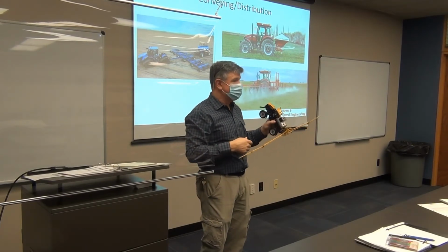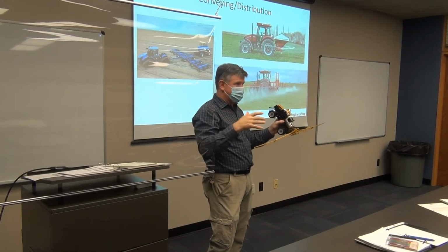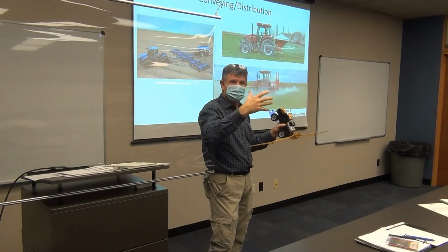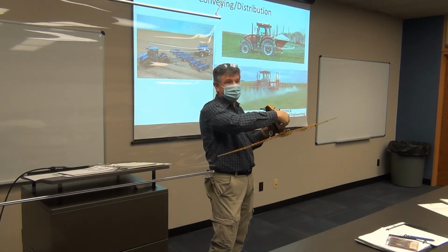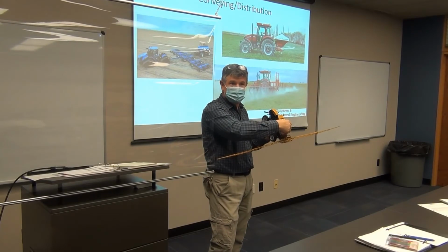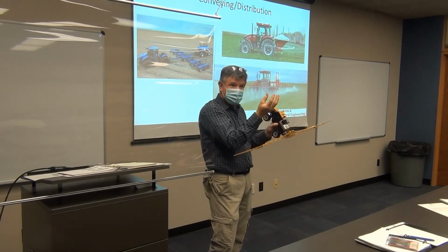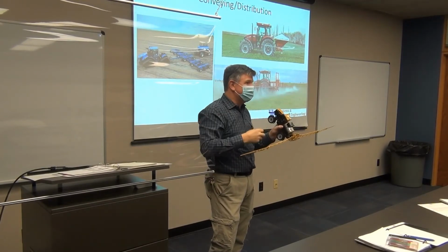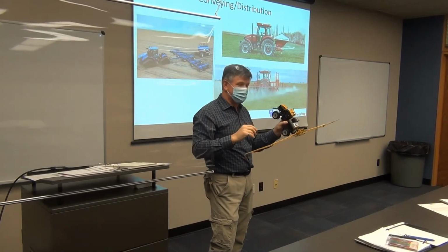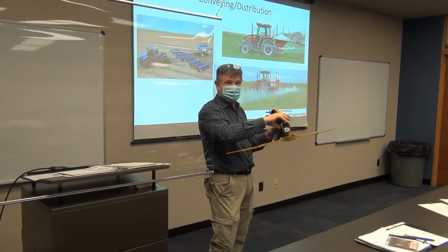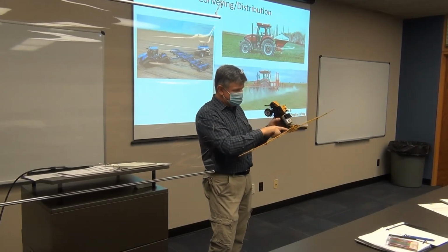So whatever chemical we have, we figure out, okay, I've got 1,000 gallons of water. How fast am I going to go? What's my application rate that I need? All that stuff that I did on the videos. So how many gallons or ounces or whatever I'm putting in here. Sometimes, in 1,000 gallons, we may be putting literally half a cup of material in there, and that gets diluted and becomes effective out in the field. So, some pretty potent stuff. Sometimes it's gallons of stuff that we put in there. But anyway, we mix that chemical in there, and then it gets pumped and distributed.